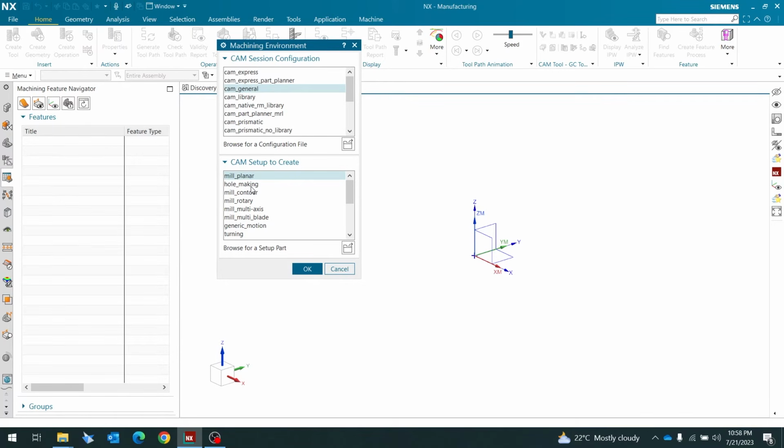So it will come to a certain position, the movement of the cutter will stop, and the table movement will start. Your cutter will come to a certain position and your table will start its motion in the XY direction. That we call 2.5 axis. Suppose your table movement and cutter movement are also there simultaneously, then we call it 3 axis.